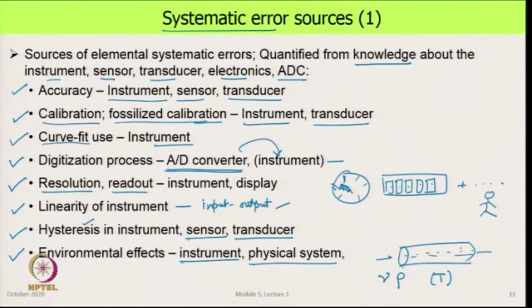So, the best thing to do would be to actually measure the temperature, even though in this case we are not doing anything else with the temperature, and use that temperature to get these values. Alternately, we could say temperature is about 25 degrees Celsius and we will get properties from the table or the book or anywhere else and use that in our calculations. The real temperature was slightly different from 25 degrees C at which the properties were taken. This variation ends up producing a systematic error.